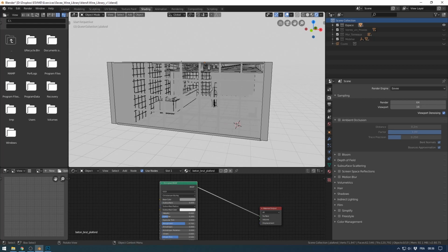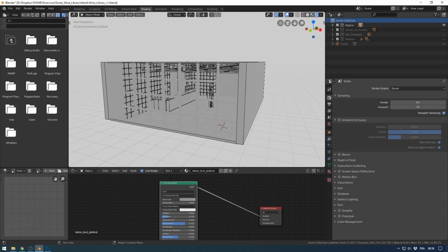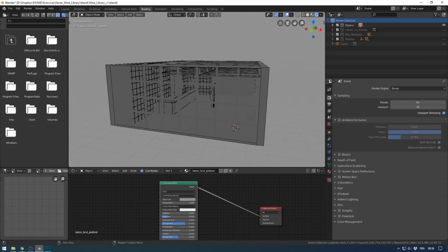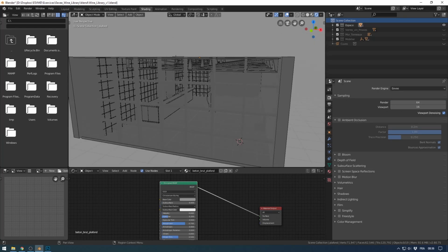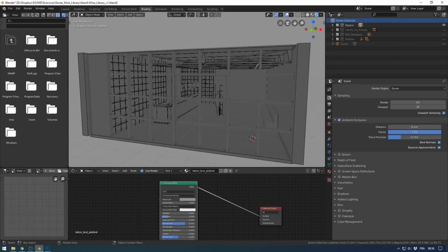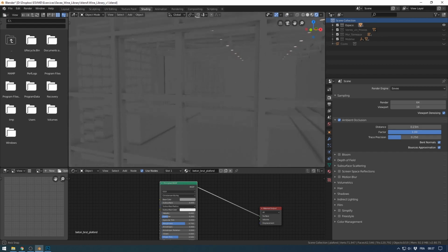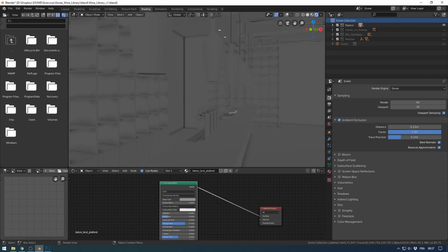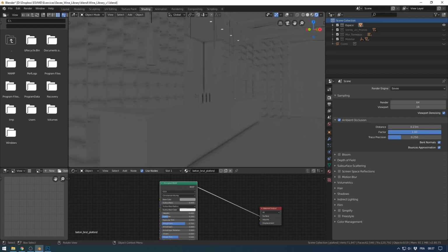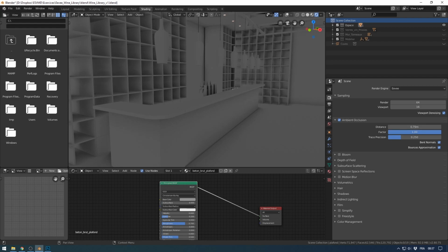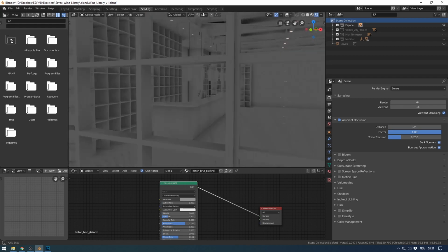First thing that I want to set is the occlusion. You will see that the occlusion is really simple to set up, because the only factor you would like to change is the distance. You can see that too low a value makes some really dark edges here, not really beautiful. So probably it's better to set a distance between 1 meter and 1.5 meters, etc.